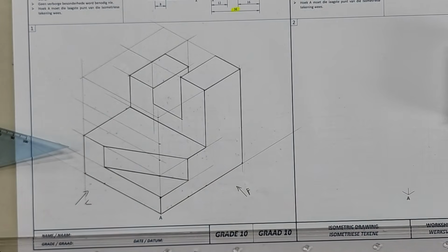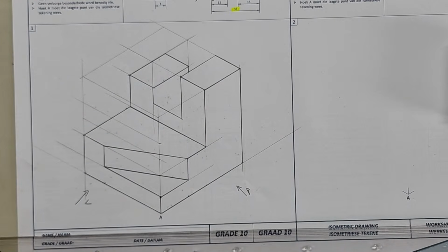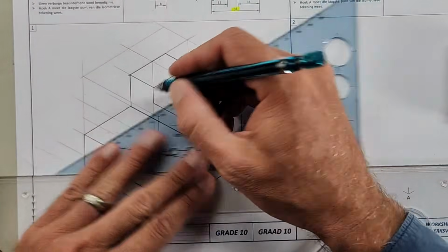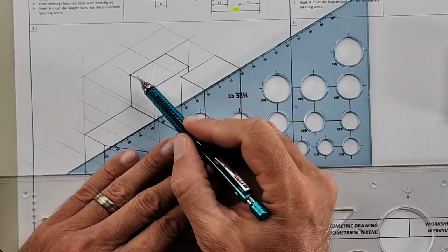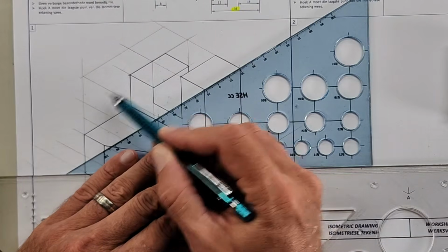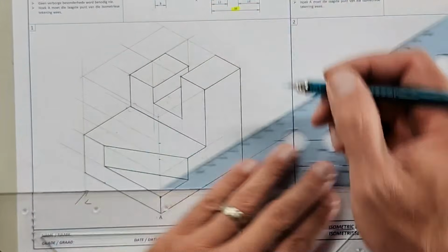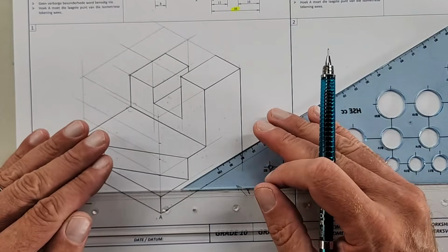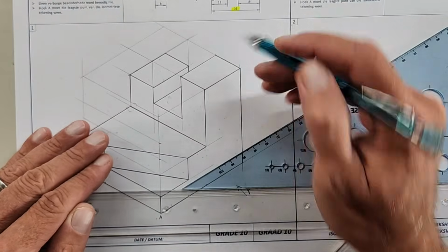Now I look at my drawing and I ask myself, is there anything missing? What's missing? Can you see it? Yeah, there's a corner. When you have two lines, always find two lines and double check if they need three lines, because you can see here, when they are front facing, there's going to be three. There's three. There's most of the time three if they are in your face. If they are at the back, there's two. Most of the time. Okay? But you can always double check.